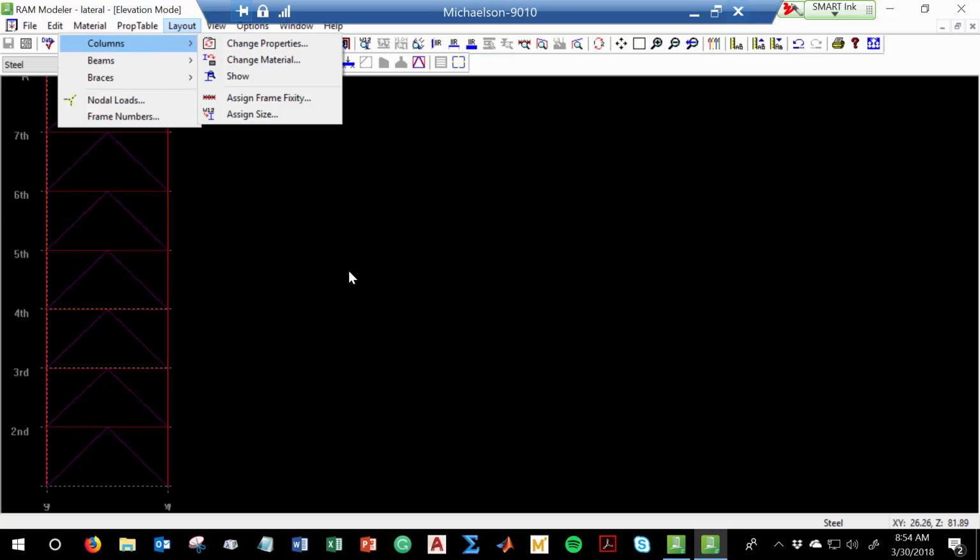I get what you're saying, but here's the thing. You've got to consider that wind can hit from anywhere in 360 degrees. So what I'm saying is put walls here, here, here, and here. And what you're saying is do this. It's still 4 walls. You just changed all their orientations. I would also propose that because those walls are aligned with the centroid as opposed to perpendicular, they're not going to be as effective. You want them as far away from the centroid as possible.